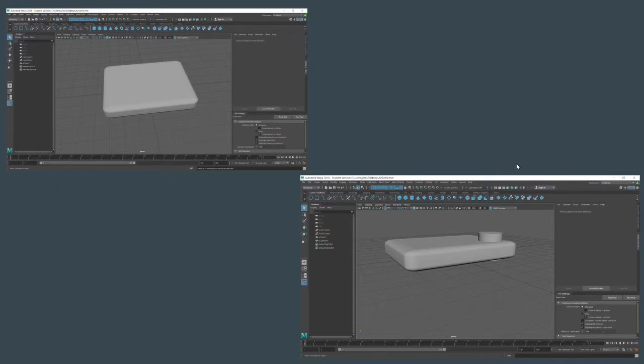rectangular body. So then to make the holes, we select the cube, and then we select all 4 of the cylinders and click on the Mesh option, select Boolean, and select Difference. By doing this, we end up creating a difference between the 2 shapes. It takes the base shape that we select first, which is the rectangular prism body, and does a difference with the second shapes that we select, which are all the cylinders.